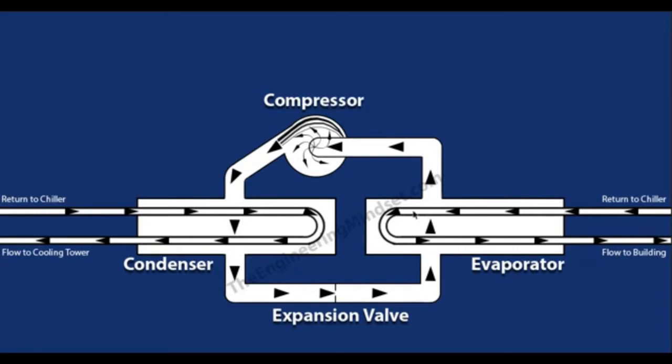You might be wondering about what's happening inside here. So the evaporator, or the chilled water circuit, is the water, if you remember, that's being sent up to the AHUs to collect the unwanted heat from the building, and that's returning at about 12 degrees, and it's coming back into the chiller, passes through the loop, and by the time it leaves again, it needs to be around 6 degrees. Obviously the temperatures can vary a bit, it depends on the setup and design of your chiller, but this is for explanation purposes.